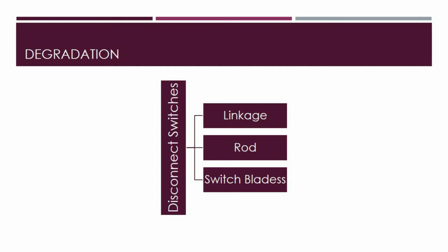Switches are rarely used for switching, but they are regularly utilized instead to decrease loads considerably below their rated capacity if need be. As a result, mechanical failure is frequently used to determine switch aging and eventual end of life. So for example, rusting of the enclosures and the ingress of moisture and dirt into the switch, causing corrosion of the operating mechanism or the degradation of the insulated barriers.